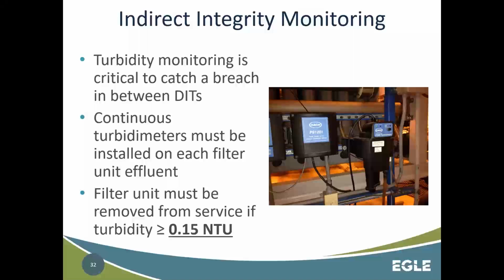Okay, and I'll also point out, these membranes are so small, you could have a failure of a direct integrity test that would not necessarily show up as a spike in turbidity. So I guess that's one thing to be aware of.